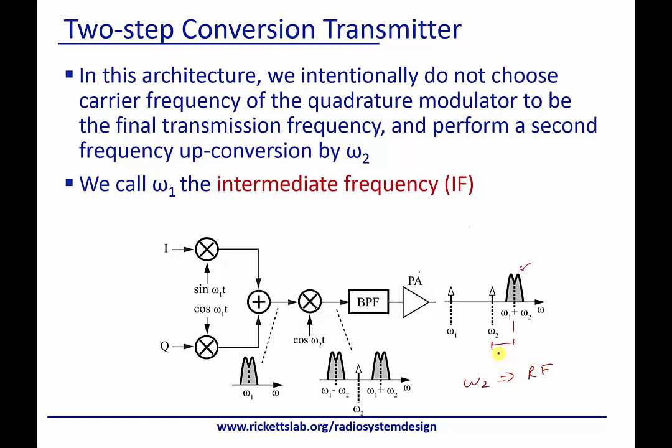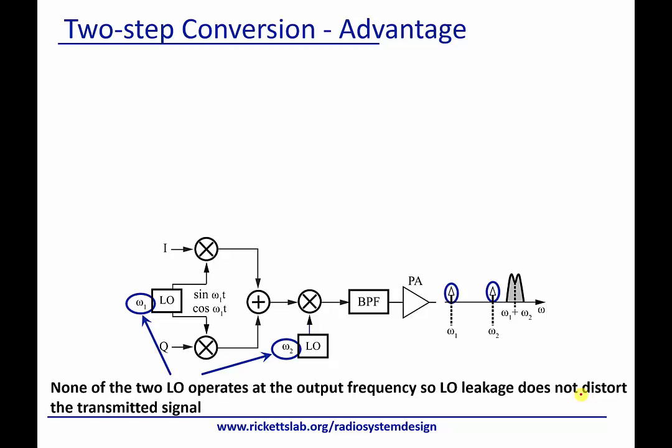And so omega 1 is really going to set this offset. So you can already think I can make omega 1 very high, and that's going to move this far over, right? Or I can make it very small, and this distance here would get closer. And so there are some trade-offs between both of those that we'll see in a moment.